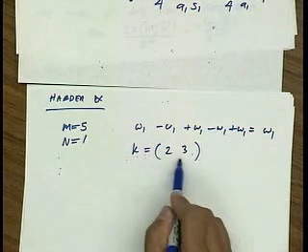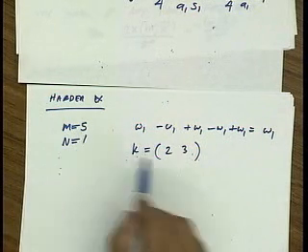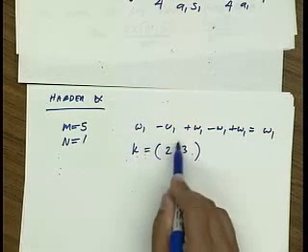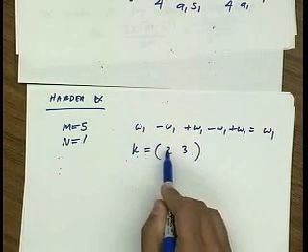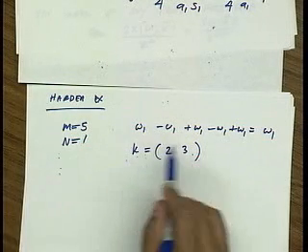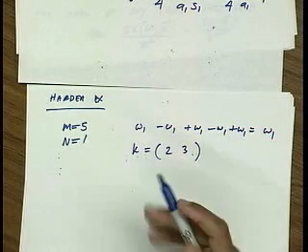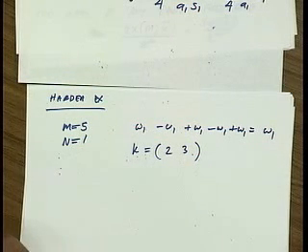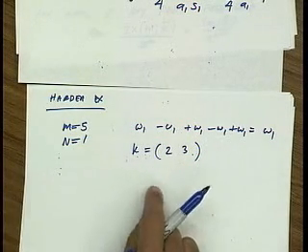So remember, 3 plus 2 is 5. It's a 5th order nonlinearity. And as long as I get 3 omega 1s and 2 minus omega 1s, I get a tone at omega 1. You can, of course, do the complex conjugate, 3, 2, get the same answer. Right? Everybody see where this comes from?